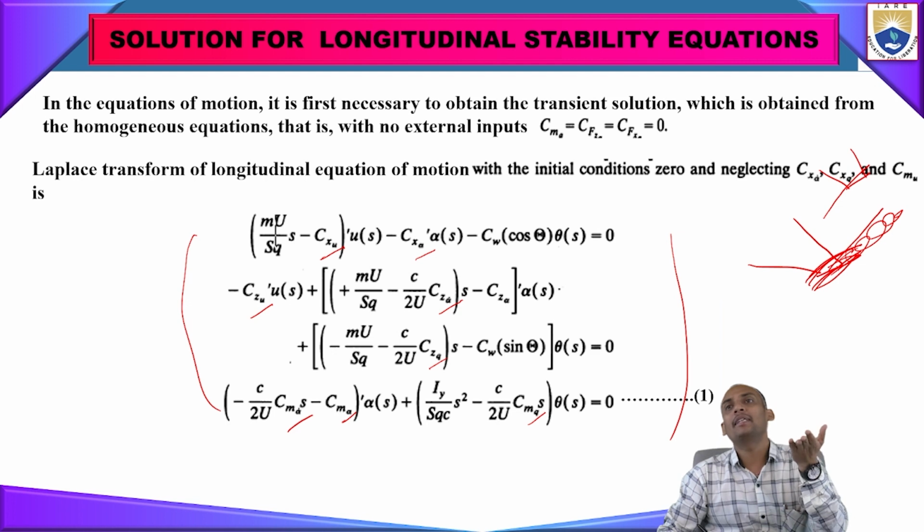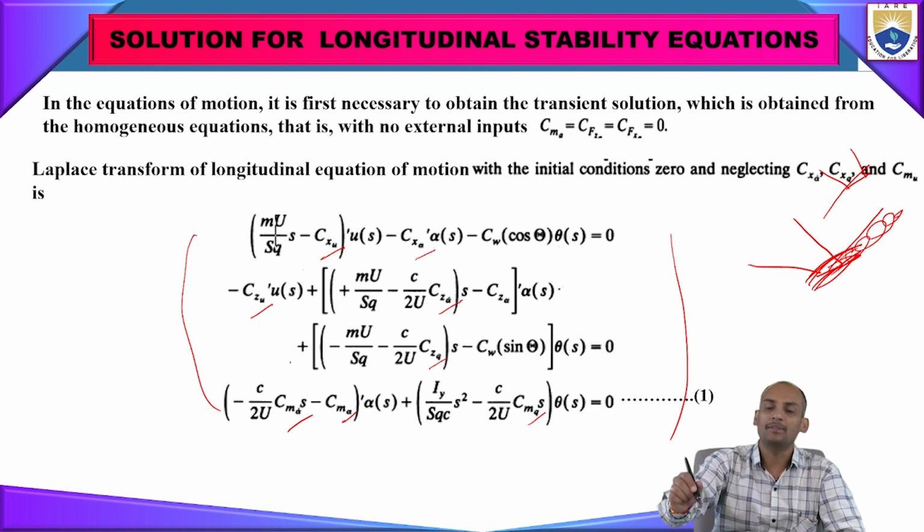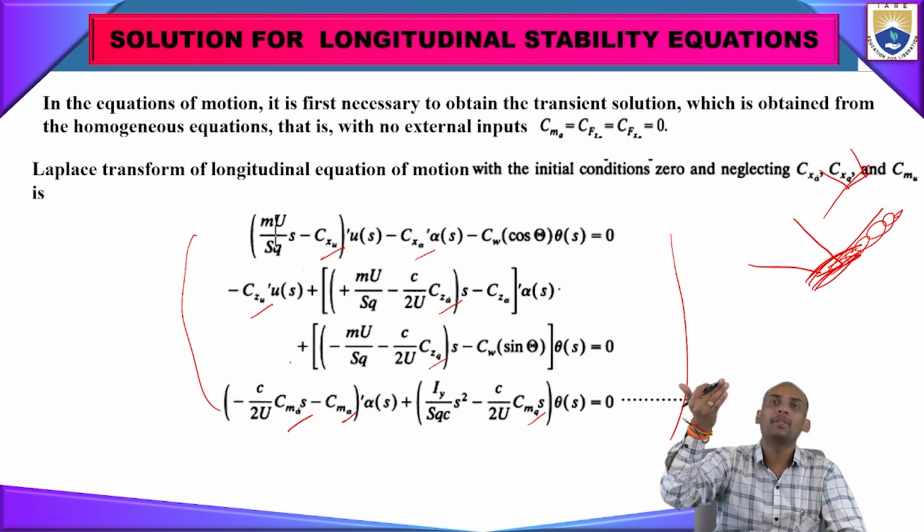Due to that adverse pressure gradient, the pressure changes continue up to the tail. For generating lift, the required condition is that the downward pressure should be high and the upward pressure should be low. Then only will we get lift in the required position. But due to the wingtip vortices, there will be pressure changes on the upward and downward sides. The downward pressure will be low and the upward pressure will be high due to the sudden change in velocities.